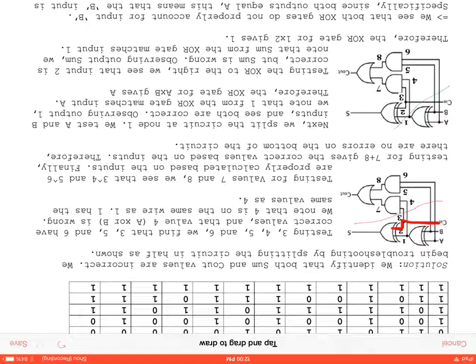The reason why there's multiple stuck at zero faults is because you designed the XOR gate in the cell to have the ground. So what people do is they flatten the circuit out, meaning you put all the metal together, all metal one, all the polys, all the pins, everything together, VDD. You find this ground, it doesn't fix your problem. You mess with it, you mess with it, you mess with it. You find this one, it doesn't fix your problem because you've reset the circuit, right? So what you do instead is I tell them just fix the ground in the cell and then recompile the circuit, boom, it works.